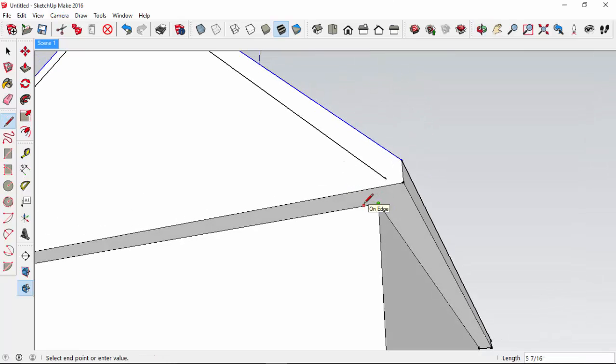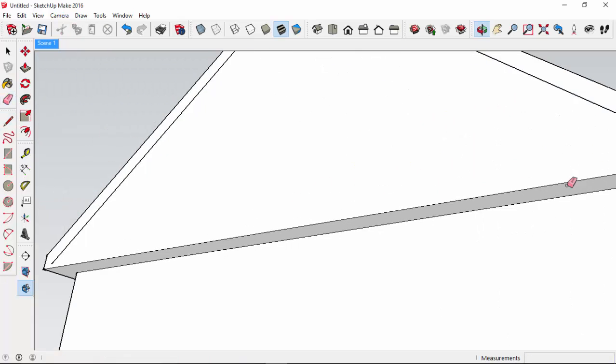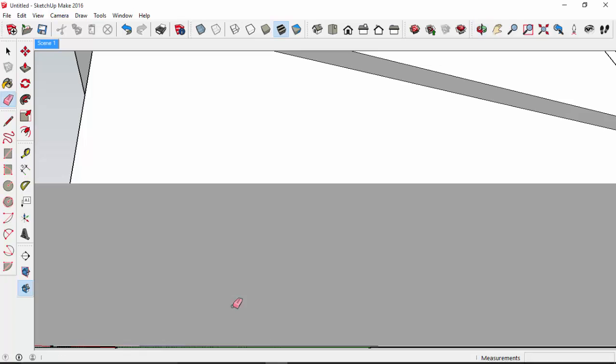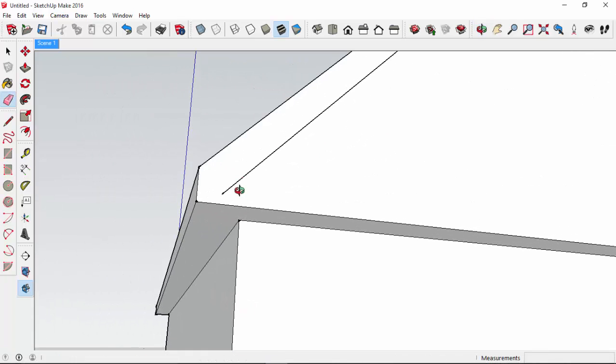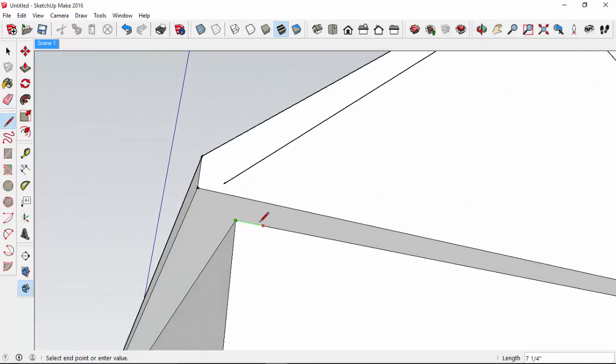and then the corner boards on the house is what I'm mimicking here, which is usually 4 inches or 6 inches. So I'll do 4 here. And then come out and draw that up to there. I can delete that, and I'll do the same thing on this corner. There and up to there.